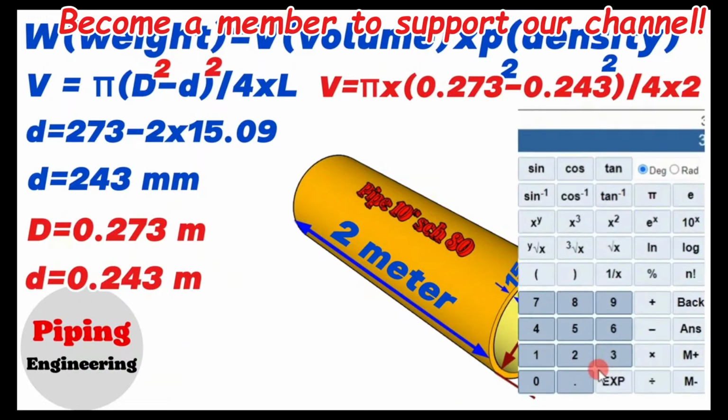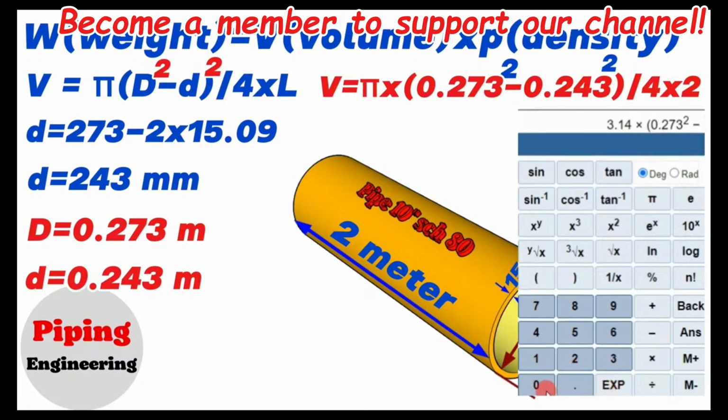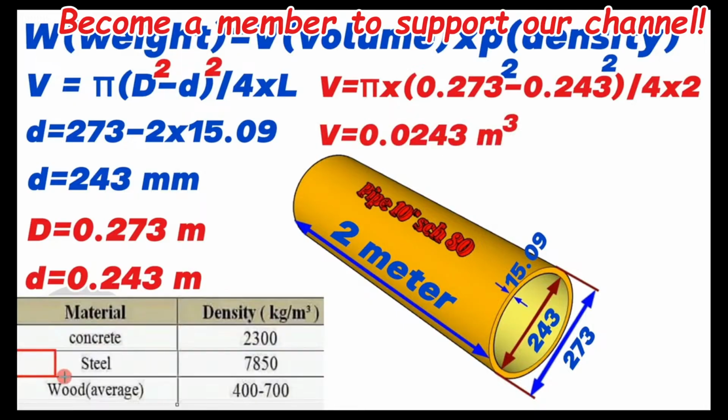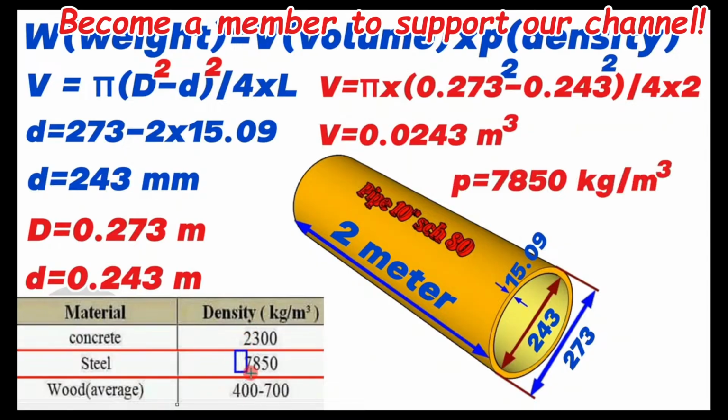Using the calculator, we find that 3.14 multiplied by, in brackets, 0.273 squared minus 0.243 squared, divided by 4, multiplied by 2 equals 0.0243. So, we found that the volume of the 10-inch pipe in our example equals 0.0243 cubic meters. Now let's look at the chart showing the density of iron material. In this chart, the density of iron steel is shown as 7,850 kg per cubic meter.